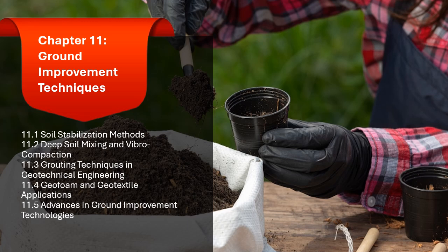4. Curing and final inspection. After the grout has been injected, it is allowed to cure and harden. Depending on the type of grout used, curing may take from several hours to days. Final inspections are performed to verify the extent of improvement and ensure the desired outcomes, such as reduced permeability or increased strength.